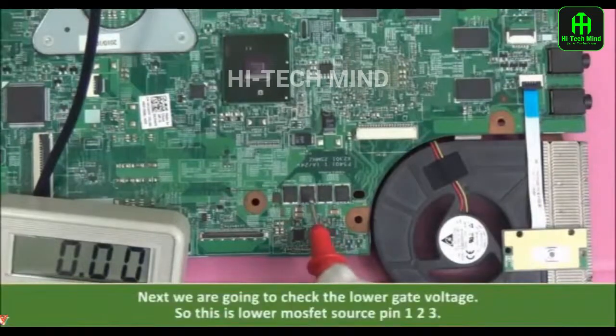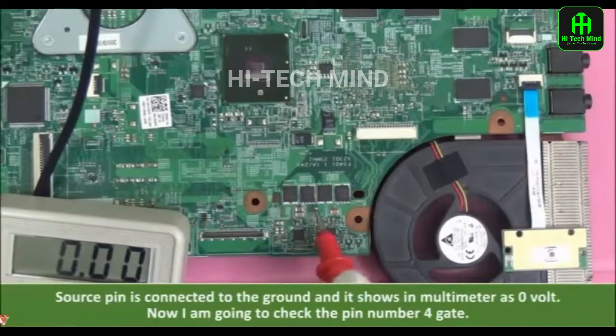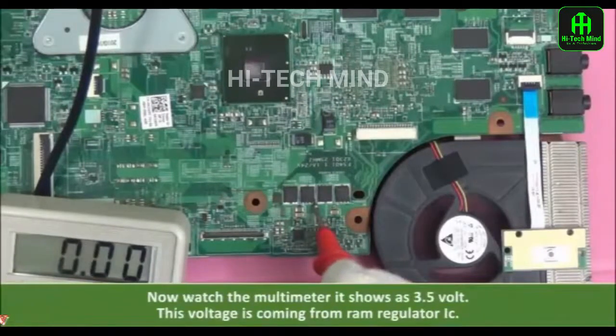Next we are going to check the lower gate voltage. So this is the lower MOSFET source pin 1, 2, 3. The source pin is connected to the ground and it shows in the multimeter as 0 volt. Now I am going to check the pin number 4 gate. Now watch the multimeter.